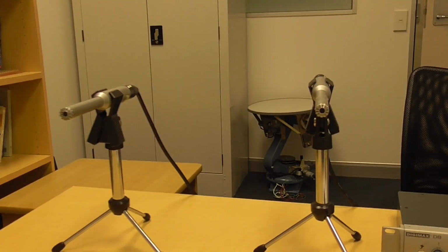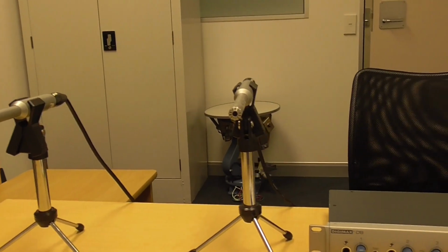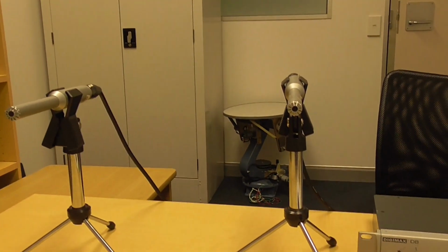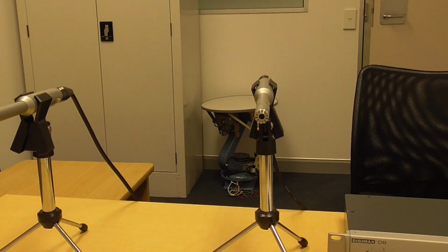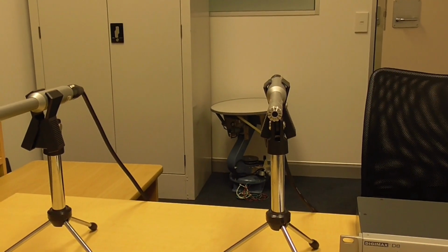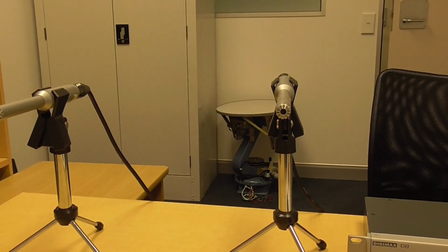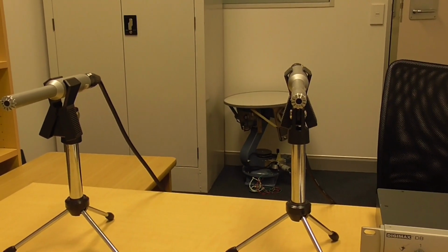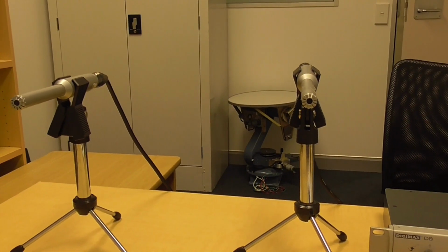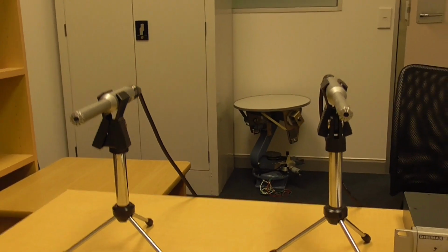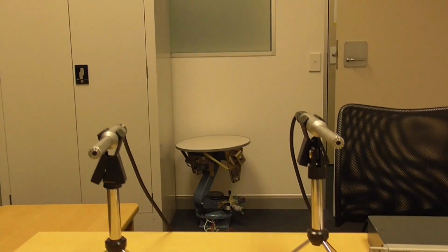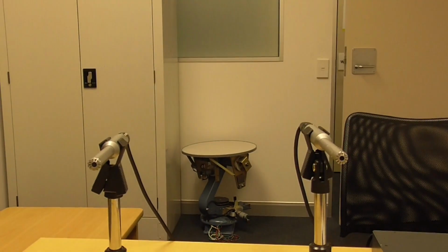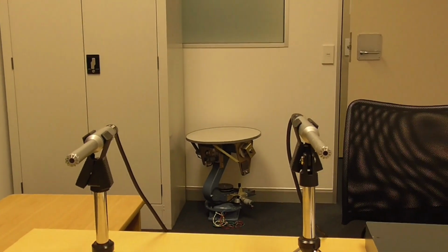And what it is, I've got two microphones over here, and of course this can be extended to more than two. And I've got a preamplifier here, and that goes straight into the sound card. The microphones are placed about 12 inches or so apart, deliberately. And the idea here is to cancel any noise that's outside of a predefined zone of activity. And the zone of activity is going to be sort of in this direction here. And actually it's behind as well. With two microphones you can't help that.